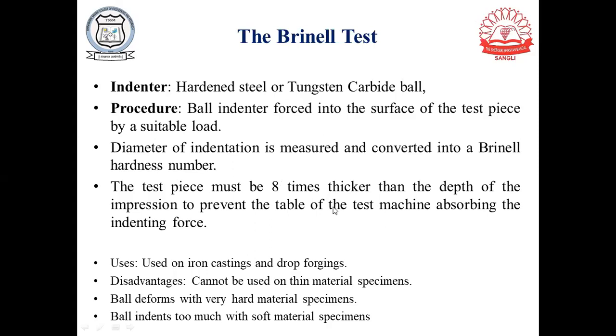Load applied by that ball indenter on the specimen is transferred to the table of the machine. Is it okay? Yes, sir. It is obviously not okay, because all the load should be carried by that specimen only, and not by the table of the machine. And for that you need to take a specimen 8 times thicker than the indentation.